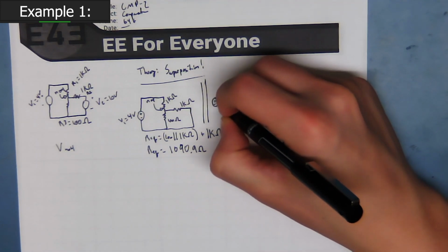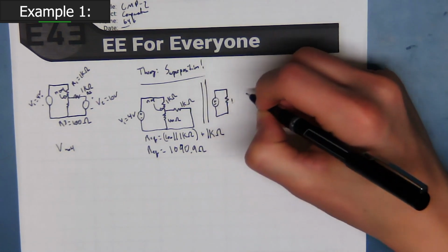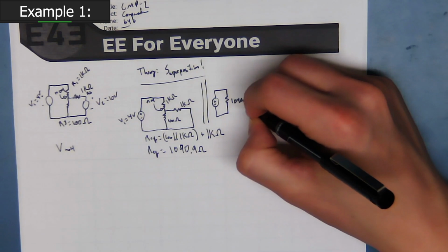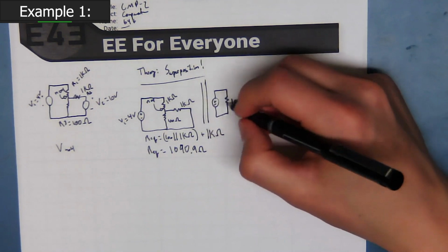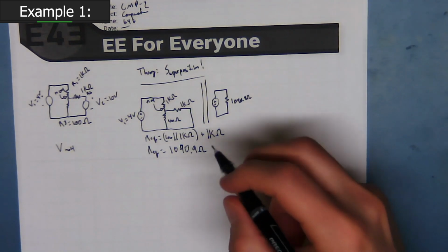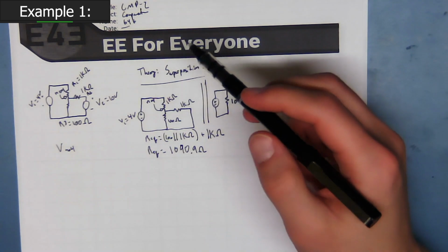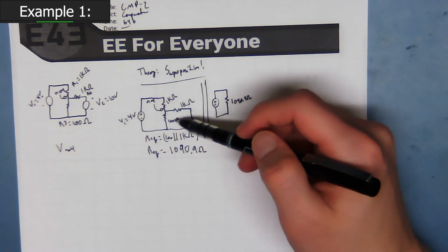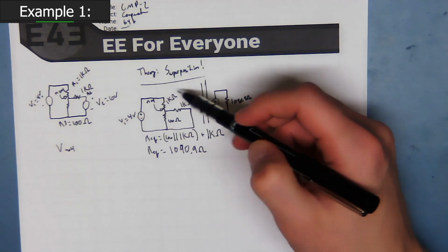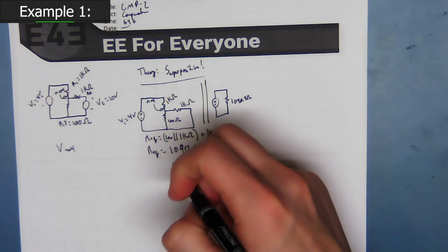So basically, if we would draw this again, basically what I'm saying is these are the same thing. As far as that voltage source is concerned, that's the equivalent. These are equivalent. So what do we do to translate this into our final answer? All right, we're looking for node 4. And we know that there is current flowing. We know that the parallel combination of these two is 90.9 ohms. We know that this total effective resistance is 1090.9 ohms.